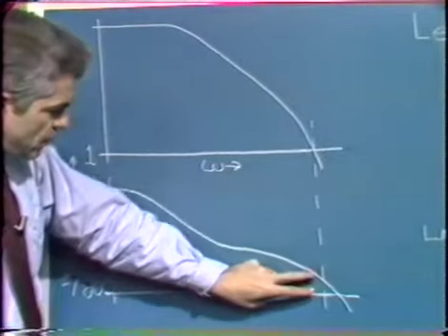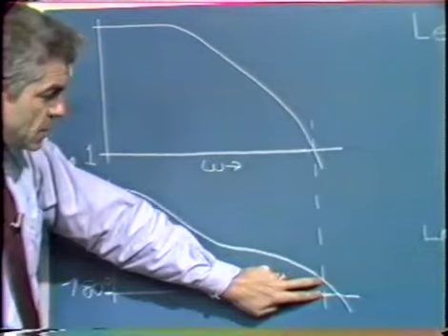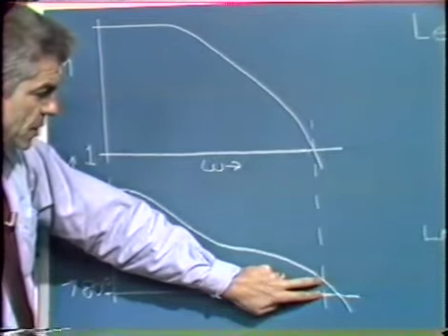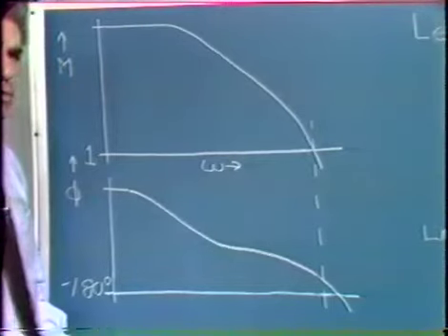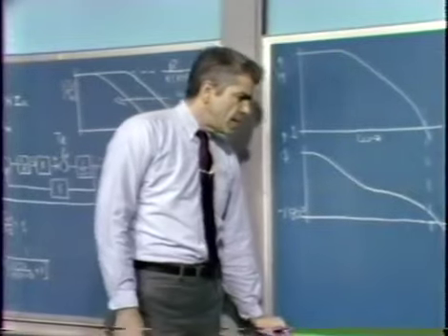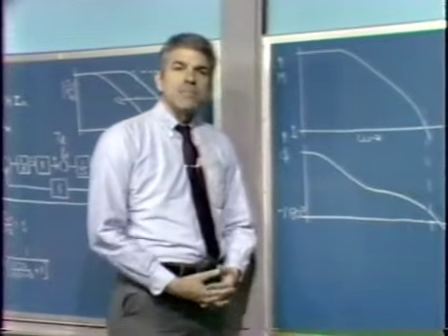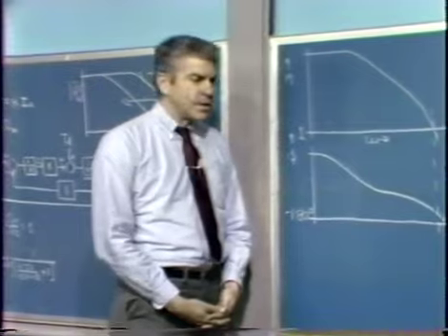But I've also tried to show in the drawing that we have a very small amount of phase margin. In this case, we might not feel that the system has adequate stability. Let's see what we're able to do to improve that situation. The kinds of modifications we might like to make are the following.